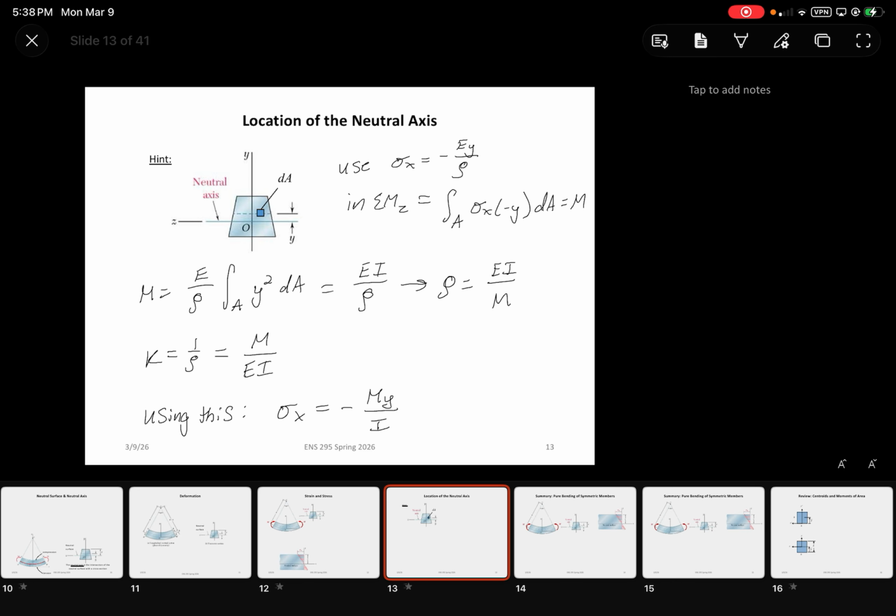All right? Now, there is one note that I want to make: in some standard cross sections like I-beams, or maybe you have seen them when you were doing your second moment area of inertia section in statics, you may have seen some term we call S. We call that the section modulus, elastic section modulus. That basically just gets defined as I over Y.